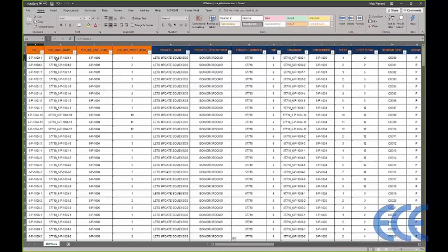I kept it pretty simple in this case just to show its capabilities, but really I'm just taking the project number and appending it to the ISO name just to show a little bit of the capabilities of renaming and updating continuations. The next 2 columns go hand in hand with multi-sheet control. So essentially, if your ISO in the model is just the 6T-1000, it doesn't have this -1, -2, so this one ISO can span multiple sheets.